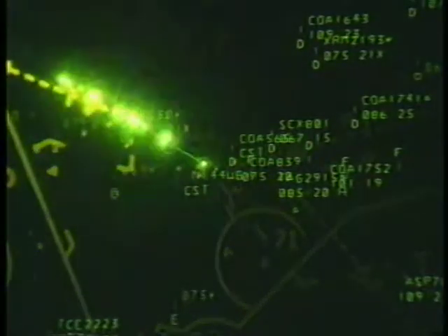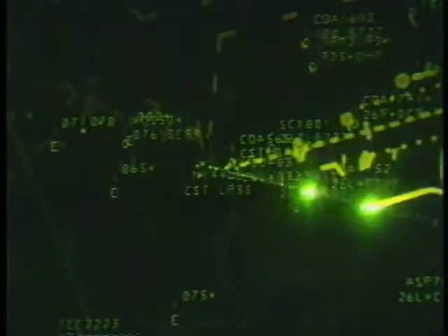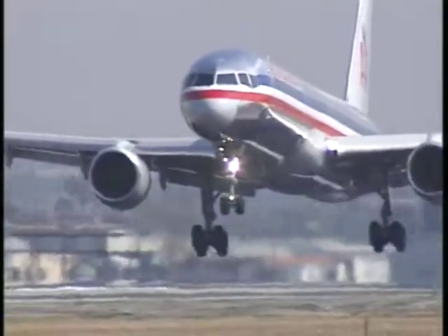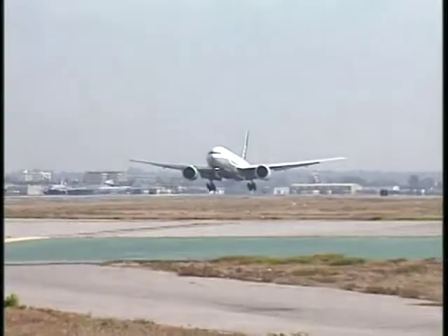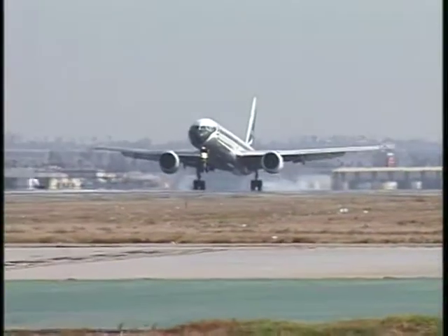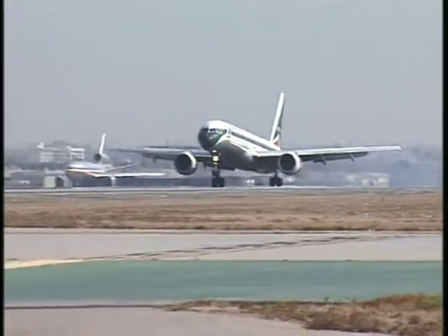Basic radar service provides participating VFR aircraft with traffic advisories and limited vectoring. The controller may help you spot traffic by letting you know its approximate location relative to your airplane. Other radar services, such as sequencing and separation, are used at busy airports to help controllers guide both IFR and VFR aircraft smoothly.